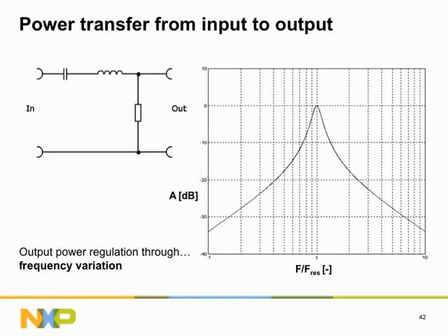Normally, an LLC resonant topology uses only the inductive side of the transfer function, the part right of the resonant peak, to control power transfer from input to output. Of course, this is a somewhat oversimplified approach of the operation of a resonant converter. But the basic idea is exactly as outlined in this short explanation. In the subsequent course module, more details of resonant converters will be presented. In order to generate exactly the right amount of power on the output that is desired, the output must be monitored, and that information must be presented to the resonant controller via a feedback loop. This control and feedback loop is not essentially different from a loop that is used together with a flyback converter.